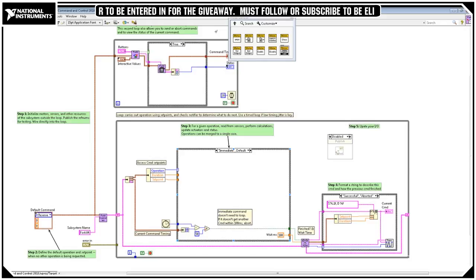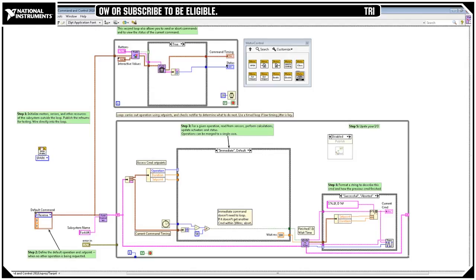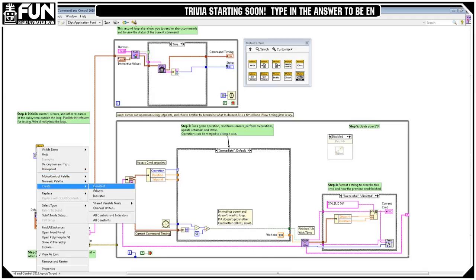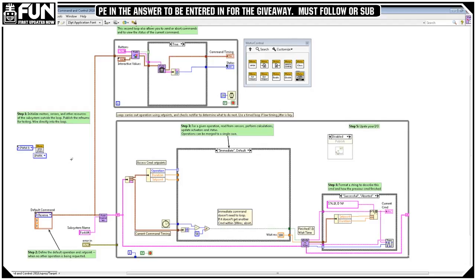So let's go ahead and add our motor. You can see I have our motor control palette already open over here. I'm going to go ahead, open up a new motor. Sure, it uses a Spark controller. Right click and create a constant. We'll say this is on PWM 9. My drivetrain is on 0 through 3. We'll put this down on PWM 9 away from those.